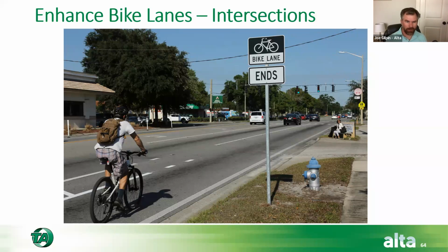So Jessica's saying it also depends on the street. Okay, so has there been much research on the effectiveness of the rumble strips at keeping people out of the bike lane? I don't know of any studies that have looked at it. I know that bicyclists actually like rumble strips if they're done correctly. They all will talk your ear off if they haven't been. So maybe you've experienced that in the past, but I typically like having them because it really provides an audible warning for motorists that might be drifting or have a little bit of inattentiveness, and that's going to stop them before they get too far into the area that they might actually come in conflict with a bicyclist. So I believe that they are helpful in that way.